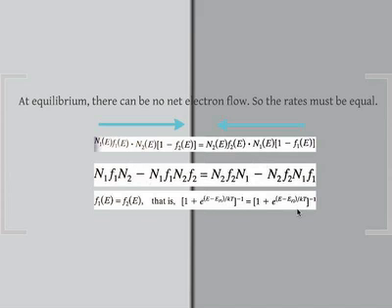Now, this is a very general principle, if you think about it, because we haven't made any assumptions as to what the material is. It can be germanium and silicon, it can be anything. All it's saying is that as long as you're in equilibrium and you're in intimate contact, such that the electrons can move back and forth freely between the energy states, then the Fermi level across the materials must remain the same. Which is a very important principle if you think about it.